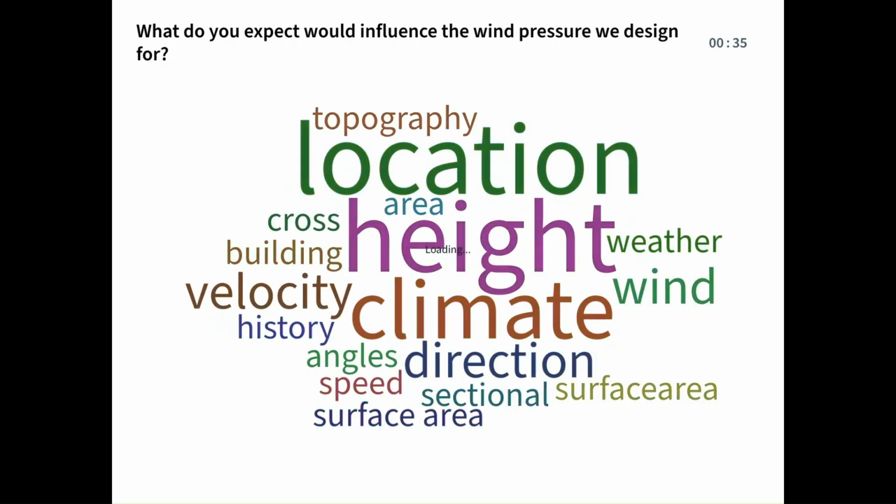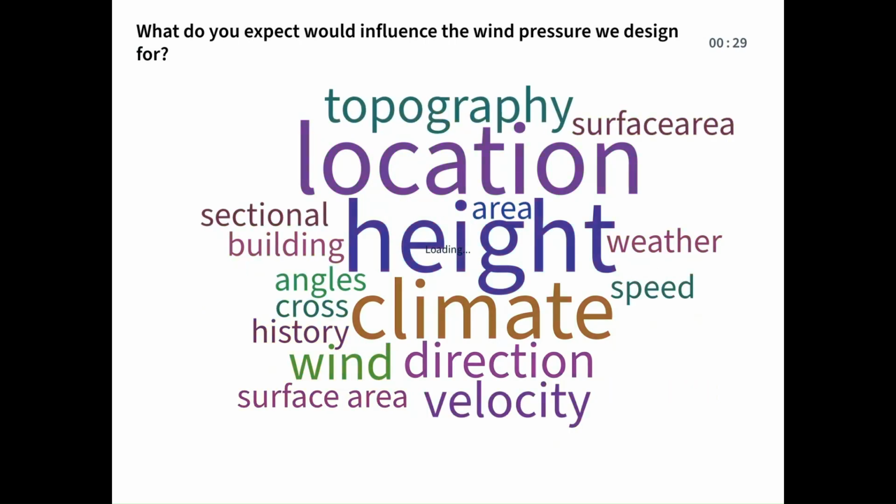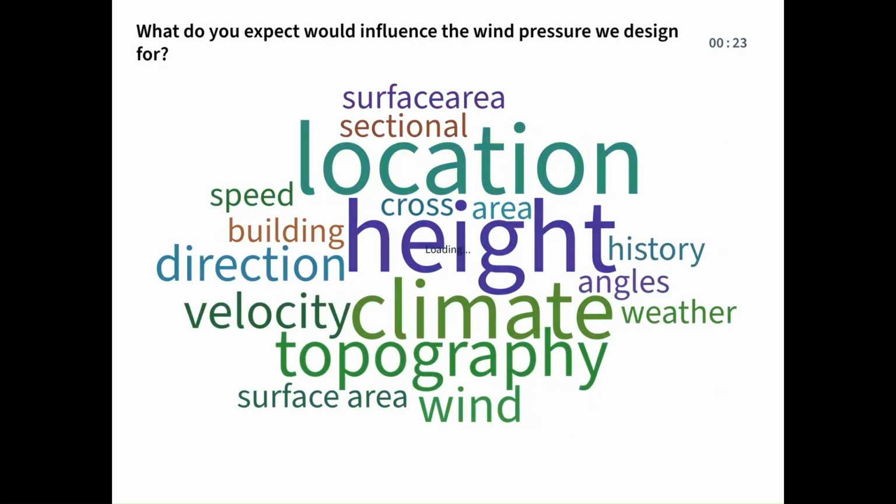Wind speed, of course, is going to be quite important here because we just talked about it. The wind speed or the pressure that a building has to resist is generally proportional to the wind speed or velocity squared. And the height of the structure, surface area, height, those tend to come into what I would call the aerodynamics of the structure, right? The wind blows by, and depending on how aerodynamic your structure is, it's going to have higher or lower pressure.